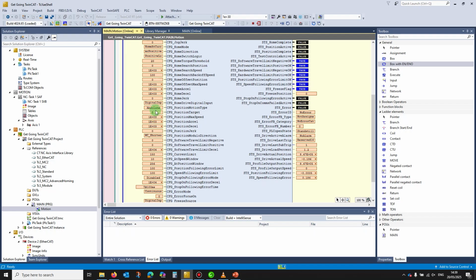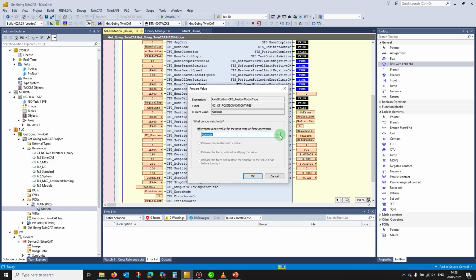Now, built into this, we have several references. So you can see here are those. So we have absolute movement, relative movement, modulo movement. So if you've got a rotary application like a carousel or something like that, you've got the ability to direct motion within a certain modulo range. But what we've also got is auto index and auto reciprocate.